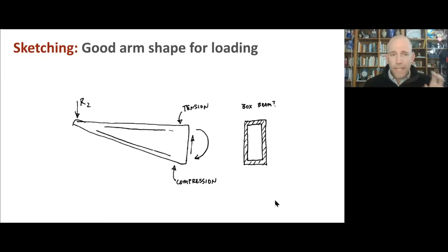If you really want to keep it truly hollow on the inside, you can use clever little tricks like printing with this surface on the bed and then modeling a few thin little beams across the top that create a surface to print on.